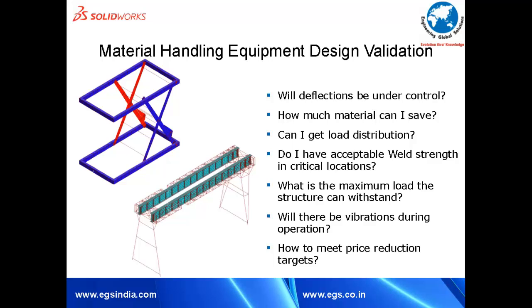If you reduce the overall structure weight, then the scissor arms become slender. The power packs required become smaller. The bearings selected become smaller. The actuating forces are reduced. The hydraulic power pack's oil consumption requirement is reduced. The pump that is required is smaller. The power consumed by that is smaller. The overall reaction time for the scissor to lift up and come down is shorter. The response is better. And now the overall cost can be seen to be coming down.